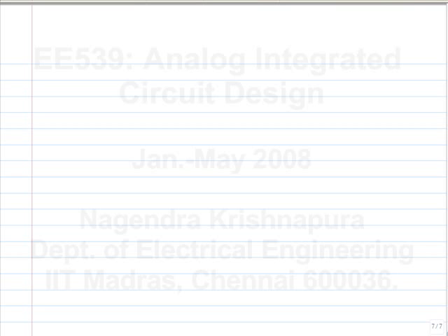So now you know how to calculate the noise in any circuit that has only resistors and maybe capacitors and inductors. Capacitors and inductors don't have noise. We won't discuss why and so on, but somehow the noise is tied to power dissipation. Only dissipative components have noise. Things that only store energy don't seem to have noise. Okay.